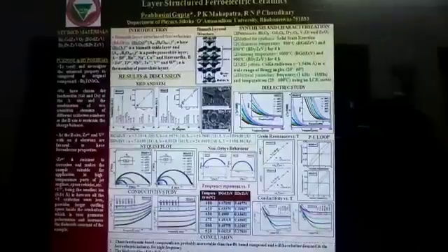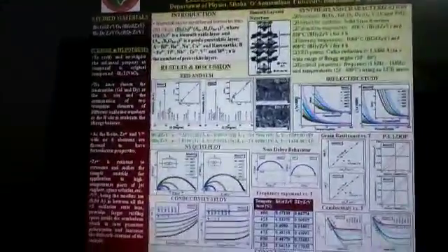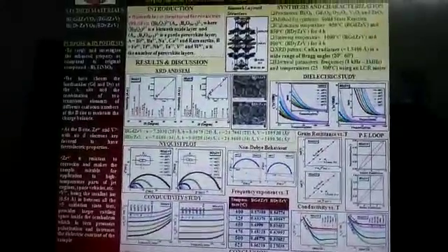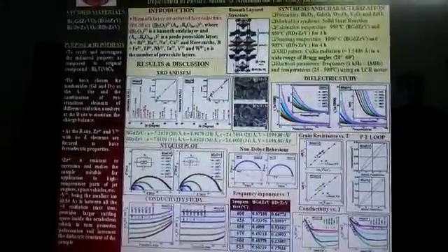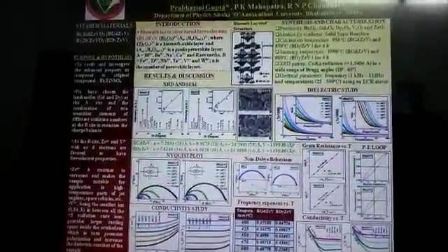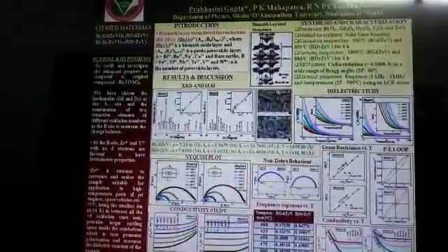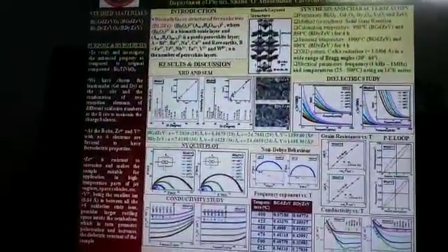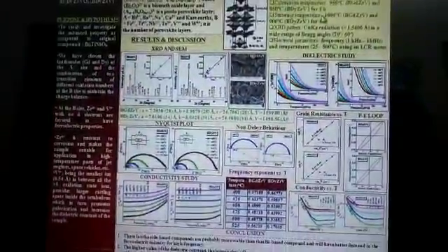The zirconium 4+ and vanadium 5+ with no d electrons favor the ferroelectric properties. Further, zirconium 4+ is resistant to corrosion and makes the sample suitable for application in jet engines and space vehicles, etc. Vanadium, being the smallest ion, that is 0.54 Angstrom among the +5 oxidation state, provides larger rattling space, which in turn promotes polarization and increases the dielectric constant of the sample.